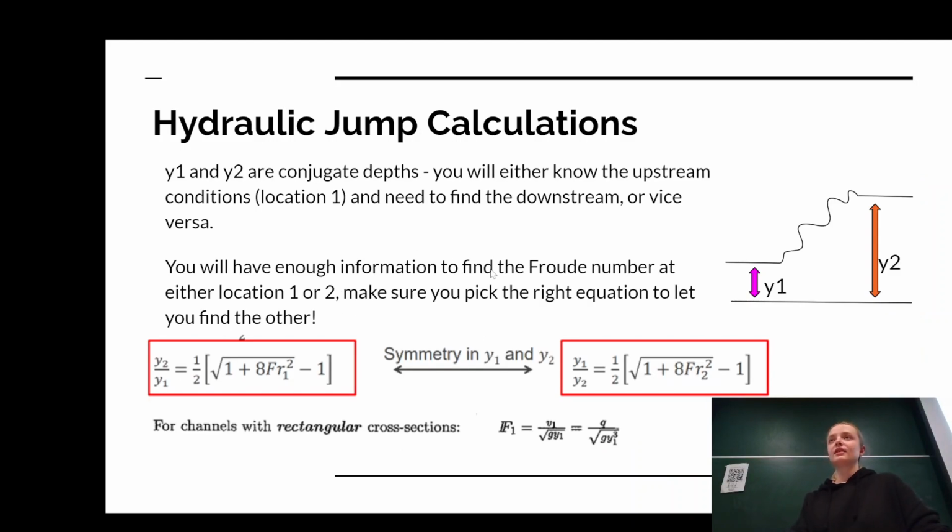Bed scarring is when you have a concrete spillway, and because of the force of the water, it starts to tear away at the concrete. So it can be really damaging for the long-term safety of a dam, and they really want to avoid that, because then they have to rebuild it. Alright. So moving into where we calculate our hydraulic jumps to occur.